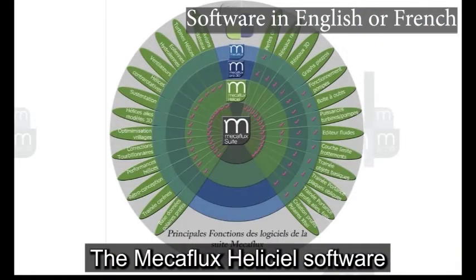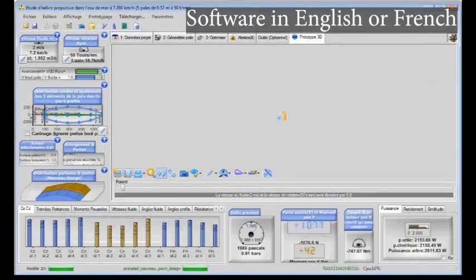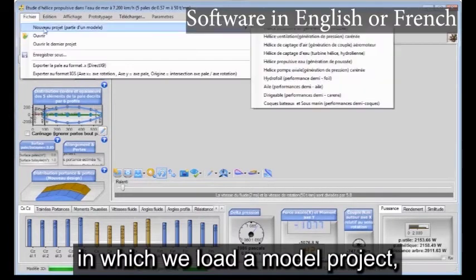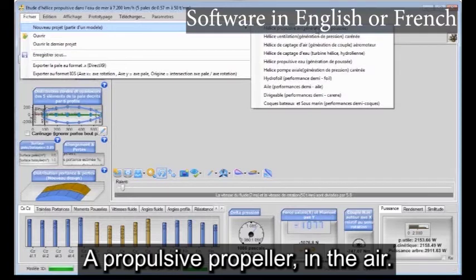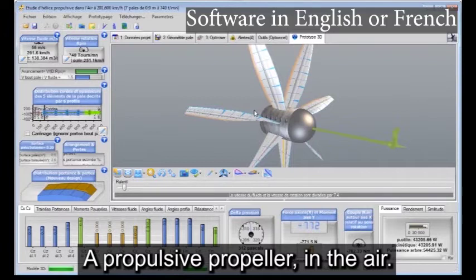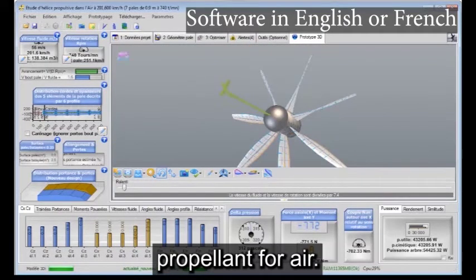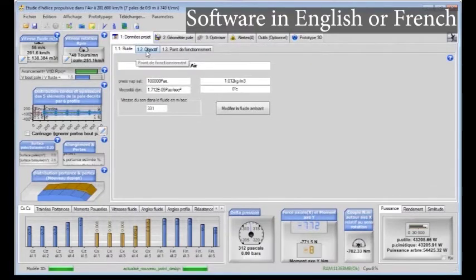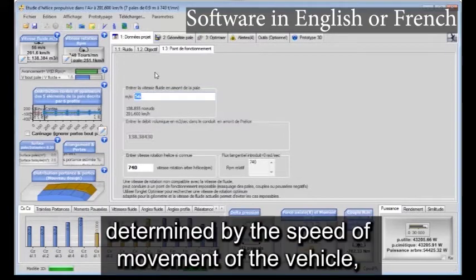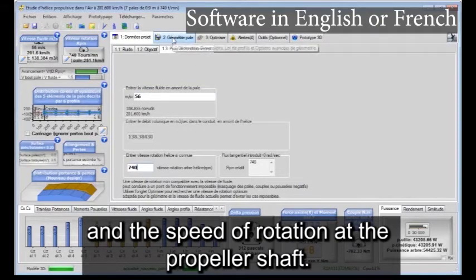The mecaflux Helisteal software specializes in the design of propellers and wings. Here is the Helisteal software interface, in which we load a model project. A propulsive propeller in the air. For this example, we loaded a propeller, propellant for air. We enter the operating point, determined by the speed of movement of the vehicle, and the speed of rotation at the propeller shaft.